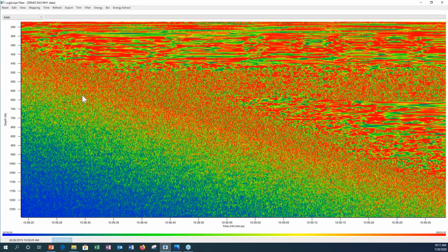And again, this data set is kind of showing something happening, but it's not so intuitive. One of the first things we like to do is there's a feature that's fairly quick. It's called binning, and it's basically smoothing the data set. So we can choose to apply a bin. In this particular case, we might want to do something fairly simple like define 5 samples per bin. That's going to give us about 1,000 bins per second. It's kind of a crude kilohertz filter, but it's just going to do some smoothing. So it's summing and averaging and outputting a particular bin.